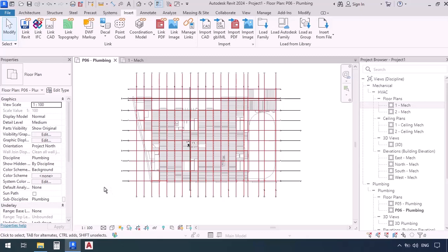Alright, so thus far we've only been adjusting some primary settings. What were those primary settings? First, we opened the right template, then we went to one of the elevations, and not only did we align the levels from the template with the levels of the architectural file, but we also named them after the ones in the architecture. After that, we went to one of the plans, and then copy monitored the grids. This far we've only adjusted some primary settings, and prepared the grounds to start modeling the sanitary pipes.